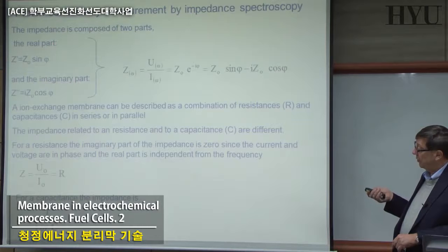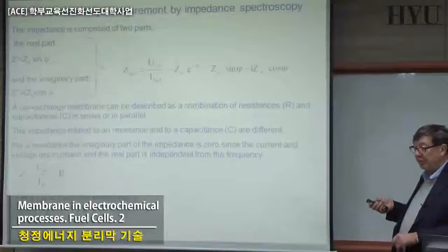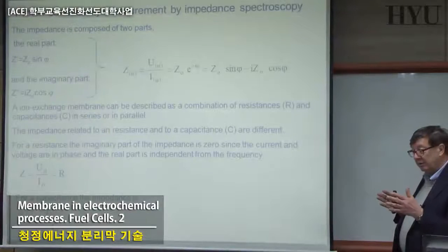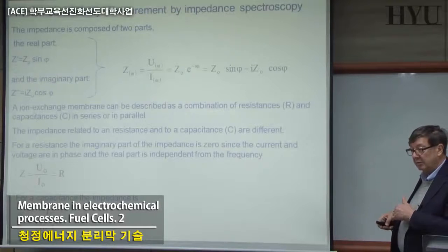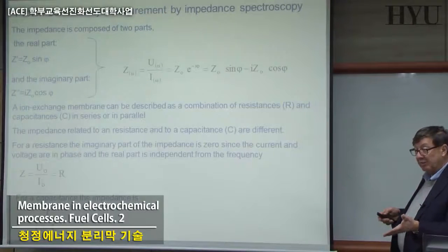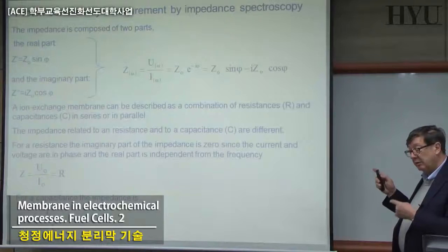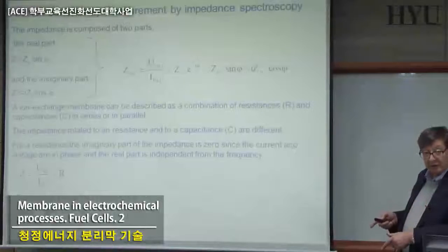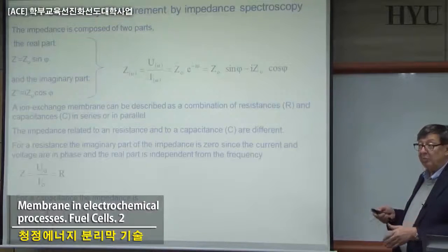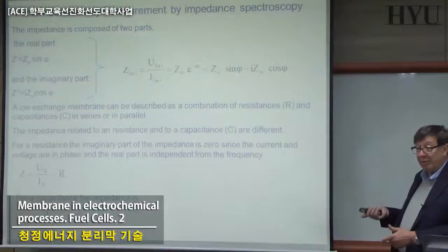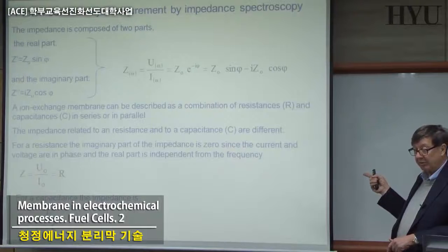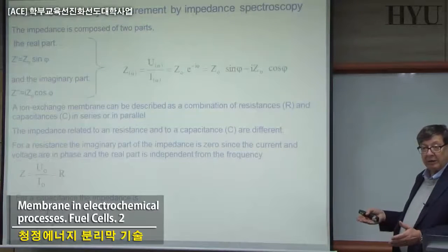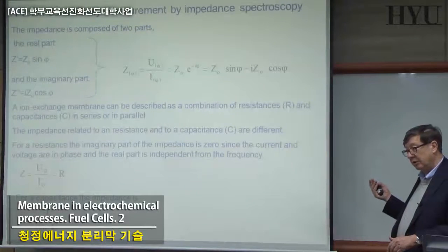Because with impedance spectroscopy you can easily differentiate between the ohmic resistance and the resistance related to the double layer or to the diffusion layer you create in the system with time. So if you want, for example, to study fouling phenomena that are taking place in the system, there is no way to make any fouling study with direct current.